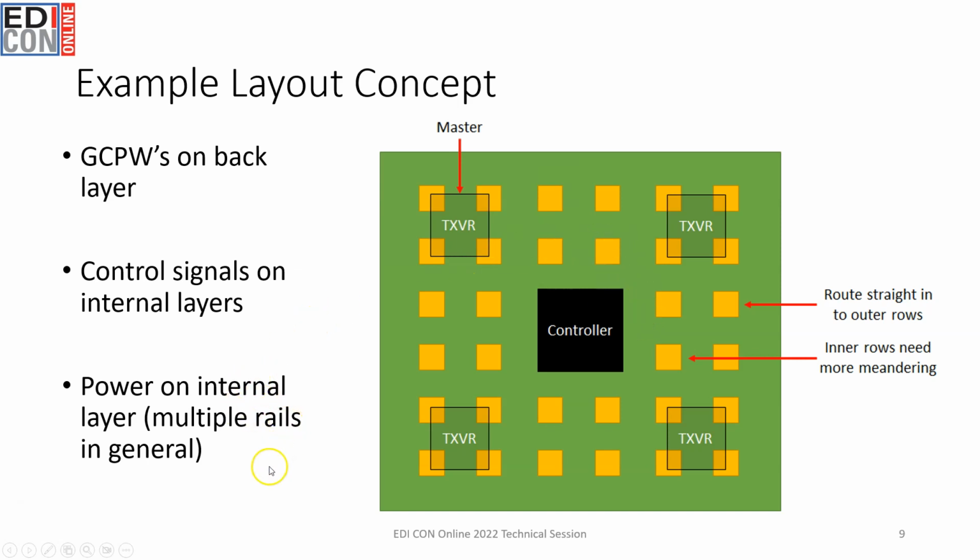Then, of course, in the stack up, you've got power on multiple rails. You're going to have multiple logic levels because these transceivers are operating at 1v8, 1v2, and probably at 3v3 for their main power rail. And then, of course, you've got ground interleaved in between all of this. So these antenna boards can reach reasonably high layer count. 8 to 10 is common, could go as high as 16. The largest that we've done is 16 layers.